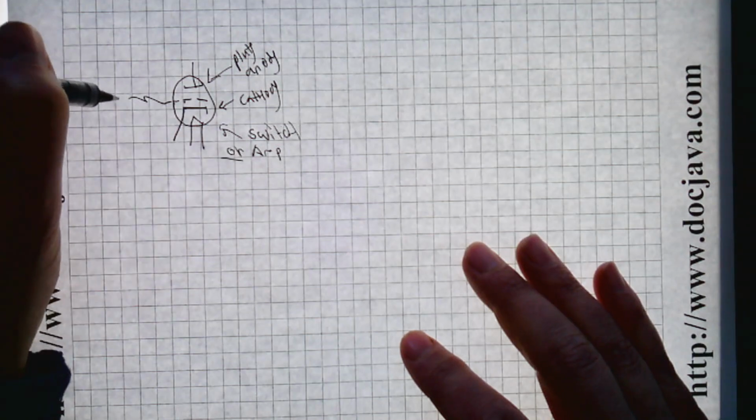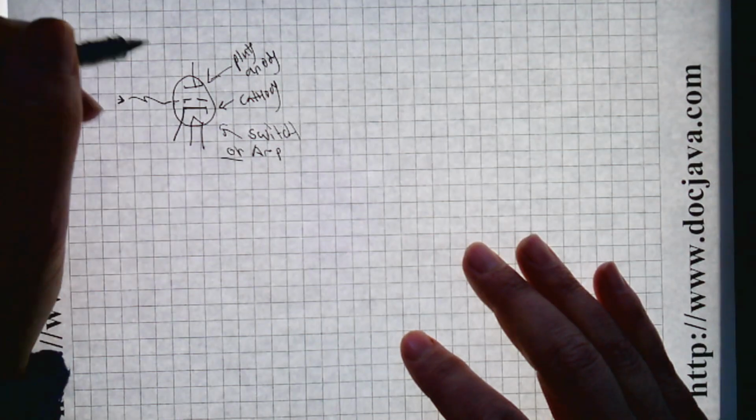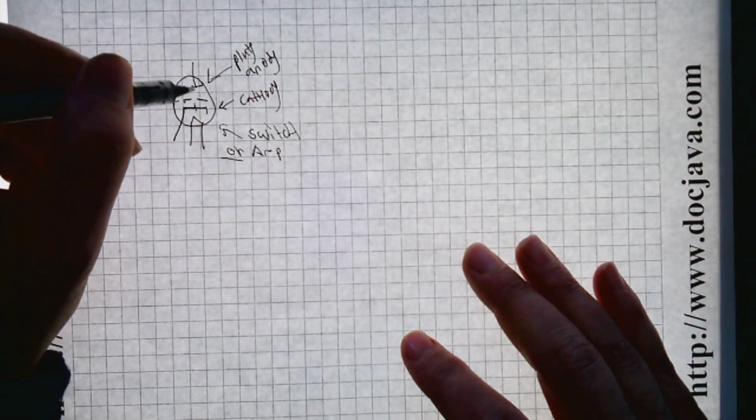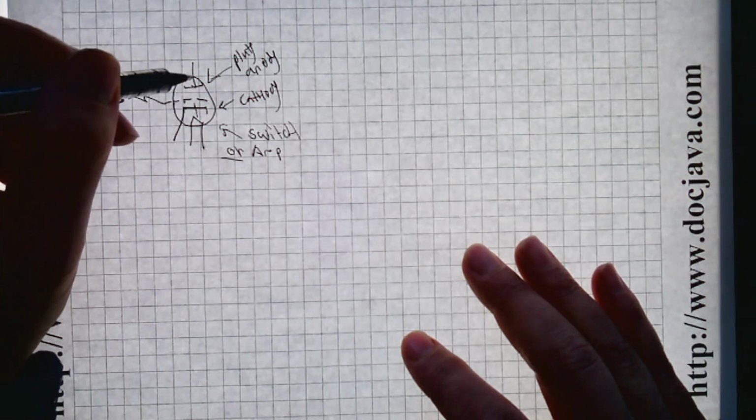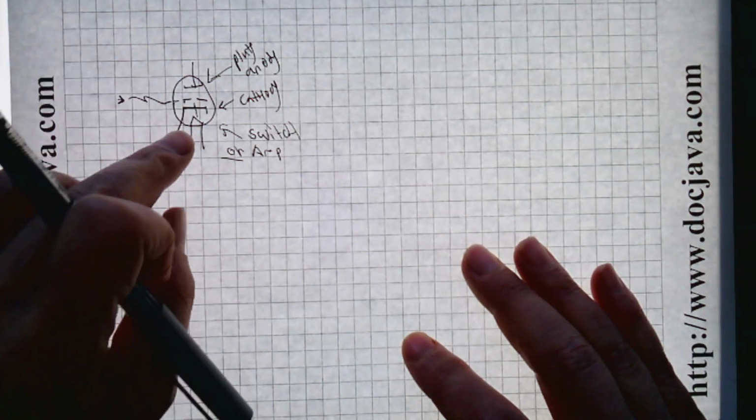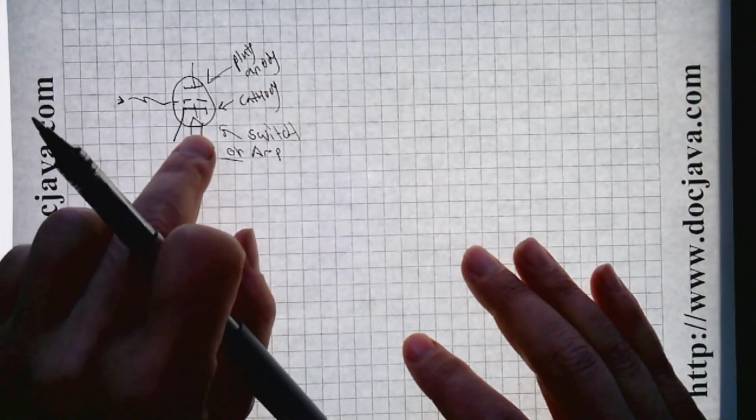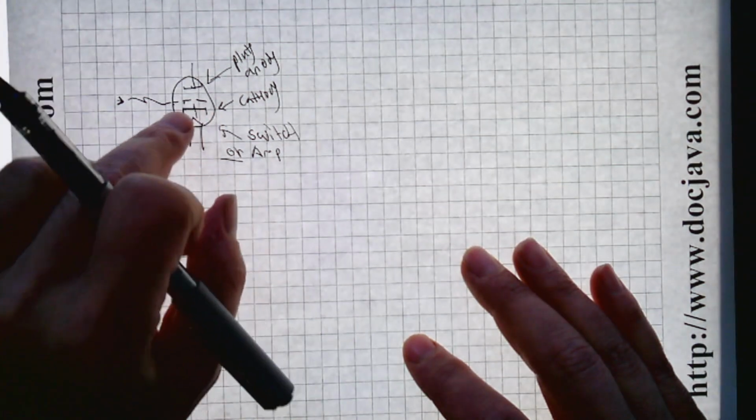And the reason why is because you can have a small voltage coming in that essentially modulates a large voltage. And when you look at the schematics for these things, the voltages indeed are large. You know, the filament could be 6.3 volts, but the plate and anode bias could be 500-600 volts. Serious voltage, not the kind of voltage like you're used to in the lab, like 5 volts. Vacuum tubes can have very dangerous voltages on them. So either a switch or an amplifier.